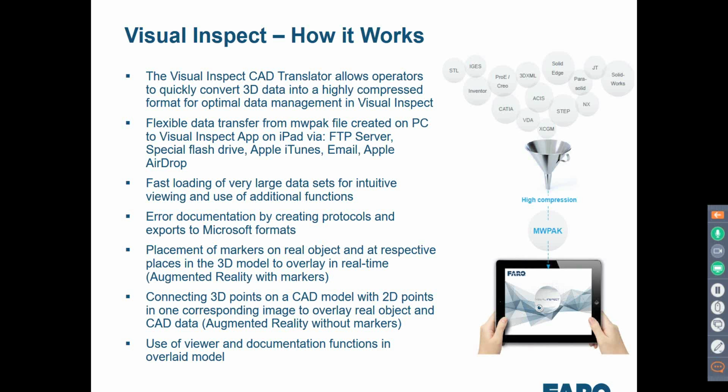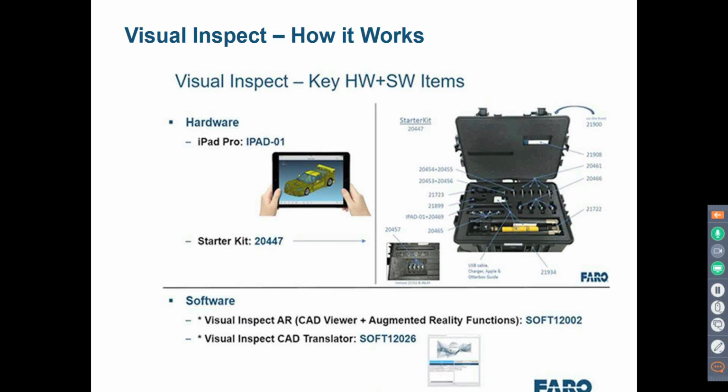Yeah, sure. There are two possibilities of doing augmented reality. We have to synchronize the real world with the CAD data. This can be done with a special marker set we created. It's very easy to attach these markers because they have special adapters in the real world. For example, stick it in holes, or we have magnetic markers or electrostatic markers for aluminum.